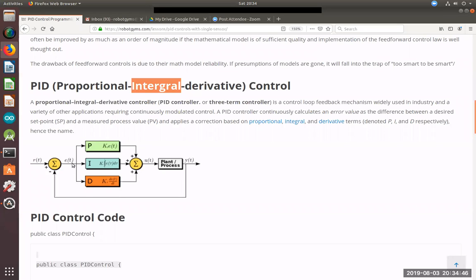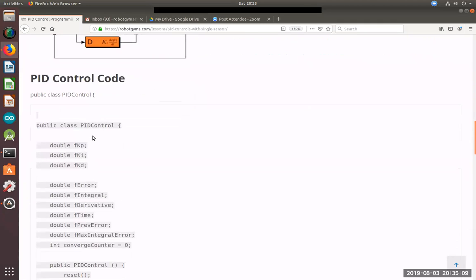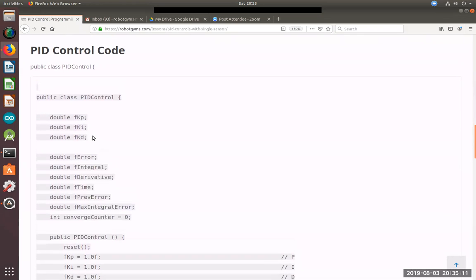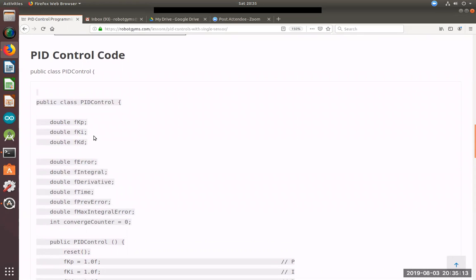And when you calculate this, you simply use a constant value multiplied by the error. Basically, you have a value times the error, the proportional error, or your historical error, your trending error. Got it? And to implement PID control, it's straightforward.